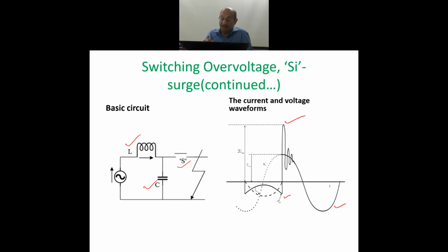So when we say here, this is the instant when the current goes to 0. If this happens, this is an ideal condition for the circuit breaker to open. And when it opens at current 0, because alternating current magnitude is fluctuating, the magnitude of the overvoltage produced is twice that of the peak value of the rated power frequency voltage.